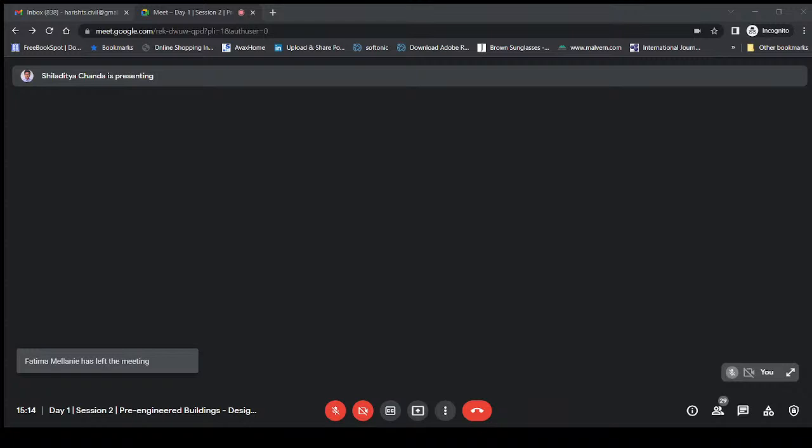This is flashings. Flashings are basically secondary framing, but used as a connection tool for connecting the sheetings to the secondary frame. Secondary frames are purlins and girts. When we attach the sheets to secondary frames, sometimes we need some further secondary framing called flashings. Here you can see this particular section is a flashing. And trims are normally taken from the sheeting material only. This is for connecting two sheeting materials into one. Suppose this is an end frame and you will have a trim over here. Similarly, in the ridge portion, when you join two sheet panels, you might put a ridge trim over there on the top of it.